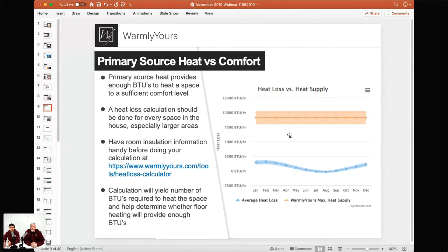Part of it. Pros would be that materials like tiles, I mean ceramic tiles, the materials with a good heat transfer ratio is something that you most of the time would want to consider, because that type of flooring will heat up faster. As soon as you turn on the system, it absorbs that heat faster compared to something like wood or carpet, right, Scott?